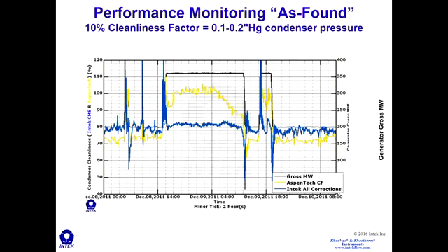Okay, so with those, there was also one more error that I didn't talk about here. They had an error in their calculation, their formula. They were using the wrong size tube, and I think there was a velocity calculation that was causing a few percent error. But the bulk of the error was the pressure sensor and the temperature sensor error. So once those were corrected, we got them to a much more usable, much more consistent metric for monitoring performance.